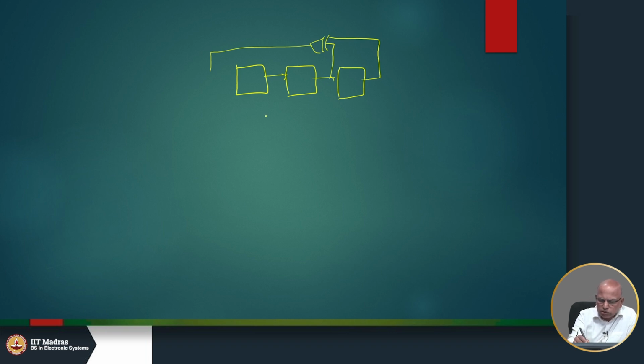If I put 0 0 0 here, the XOR of these two is 0 and it will come here and it will get stuck. Okay. But if I can recognize that it is all 0 through an OR gate, and if that can be fed back to this guy, I think that is how it works.